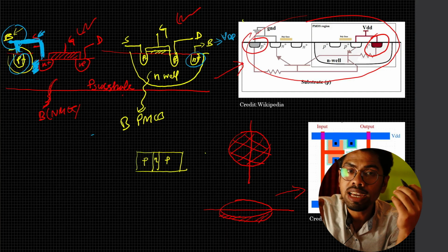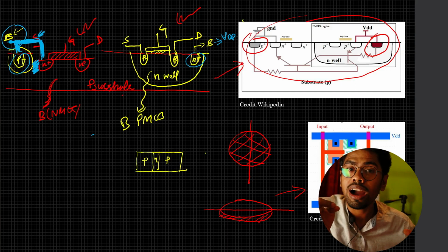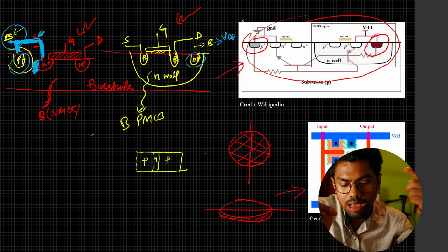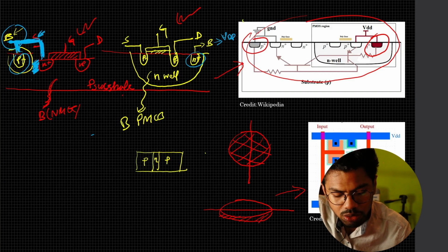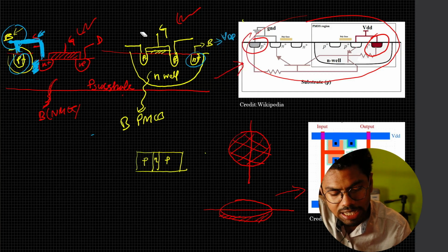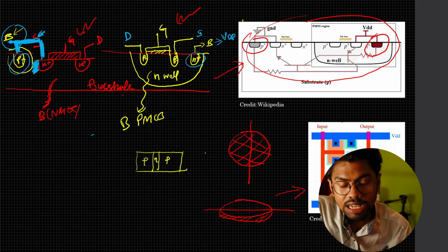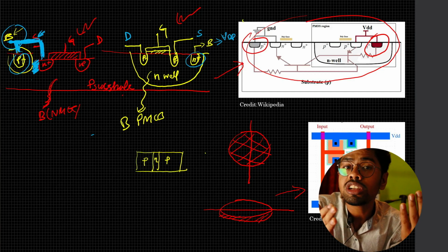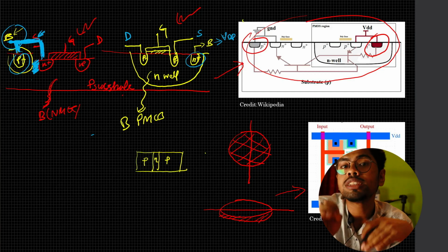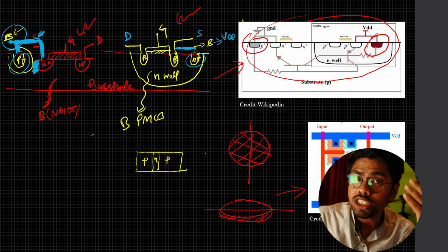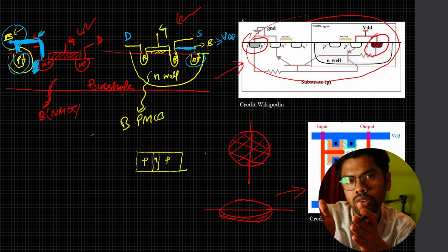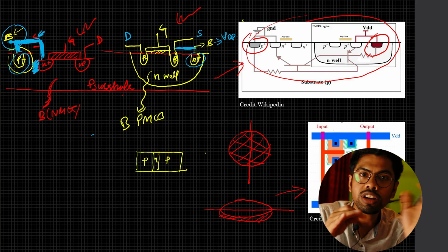But there is also another reason, and that is the second question of ours, the body effect. We will go there a little later, but let's explain it here. If I want my source and body together, I need to interchange this, and we can interchange because our MOSFET is a symmetric device, so there is no issue. The source and drain get their names according to who is supplying the electron and who is draining the electron. So we connect source and body together always, and that will help us avoid the body effect.